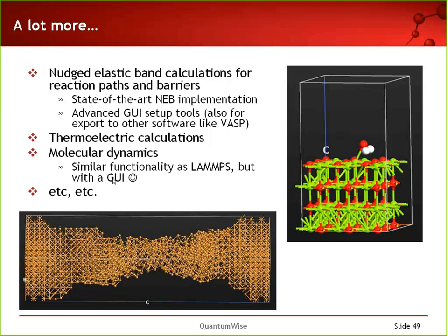We have another question. Do you have an example of ATK working with TCAD? This is a kind of a new area. This is an emerging area. One of the difficulties with working with TCAD is that some of the assumptions that they use don't necessarily hold. The very specific example is that many of the parameters that they desire, for instance, effective mass, well, the effective mass in a usual material is normally quite energy independent, at least at the bottom of the band. It may be anisotropic, but it's usually quite parabolic, the band.